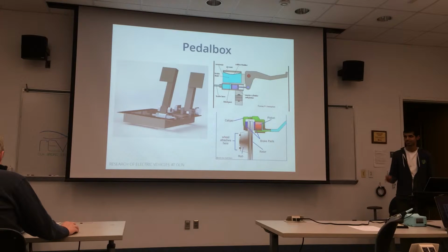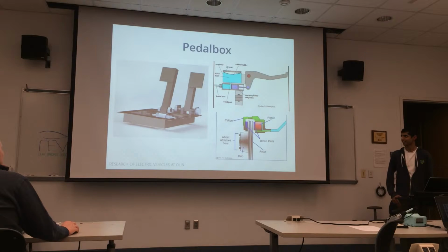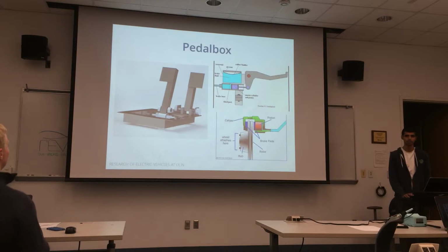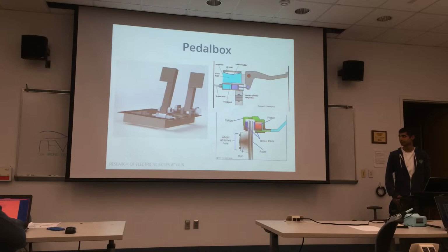Next, the pedal box. This is something Gordon worked on. The pedal box is super important, especially for you guys, because this is really integrated with sensing and powertrain. On one hand, we have the throttle, which is just connected to a pot, and this is what's going to drive the VDIF. This is really important to pass over to sensing so that we know whether the throttle we're putting down is the same as what's getting output into the motors.